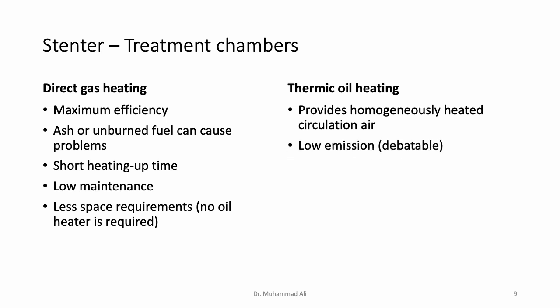Low emissions, that's again debatable. It's because if your thermic oil boiler is gas fired, that is, it uses natural gas to heat up the thermic oil, then probably you cannot say that the system has this characteristic low emission. But if your thermic oil boiler is, let's say, electric, then there is a possibility that the overall emissions of the system will be low.